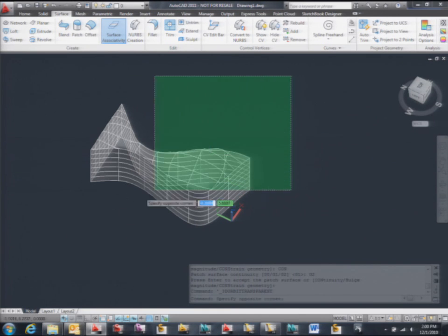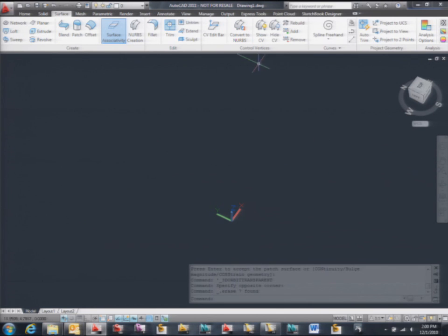So another trick when doing Spline Freehand is once you do the spline and you click enter, you will have a certain set of control vertices, right? In this case, it was a very small set of control vertices, but I'll go really far away and do another spline. And in this case, you see that it's more bumpy, right?